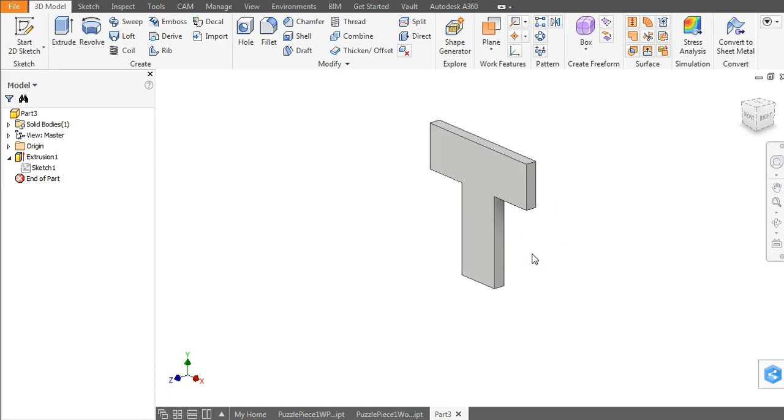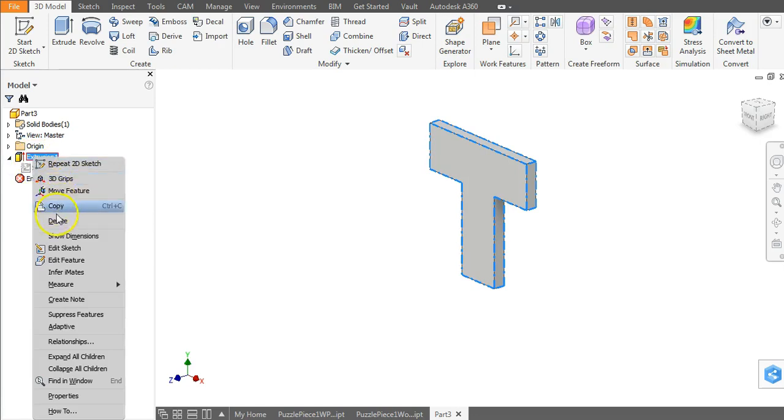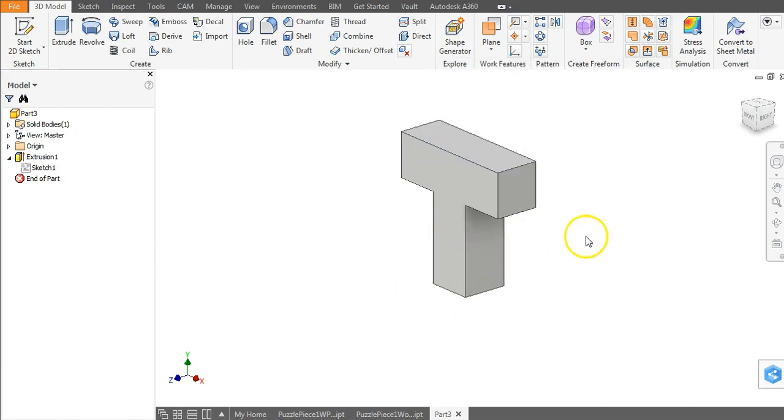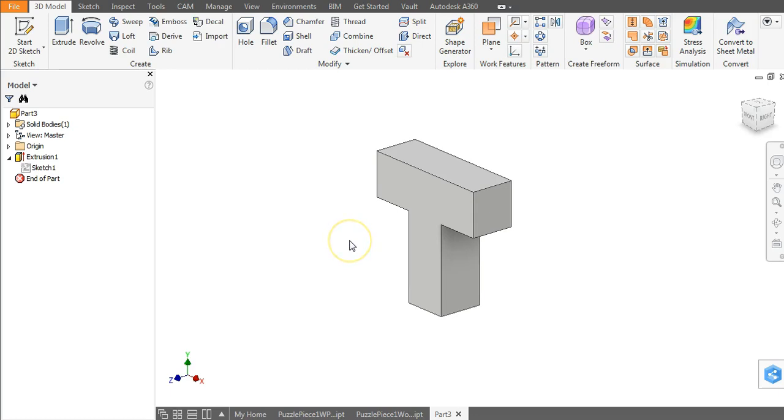Well, the idea was that the model would grow proportionally in all directions, and that is why I used a formula. And so I'm going to update that to be, again, D0. Now it's back to being proportional. I could finish by making a new sketch and adding that last little block on. It's the same thing, but I wanted you to see something called parametric modeling.